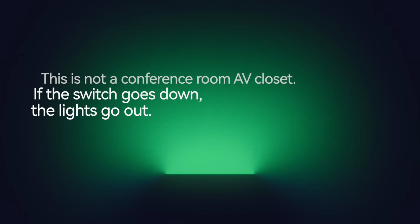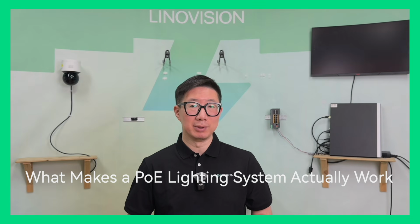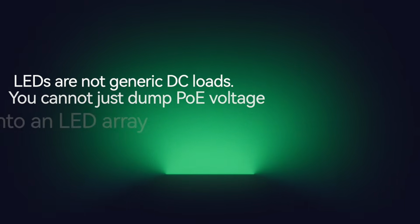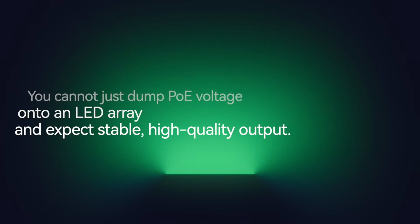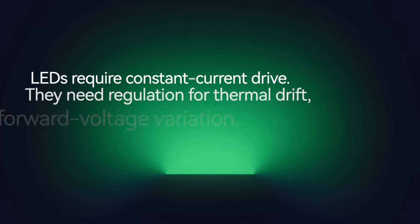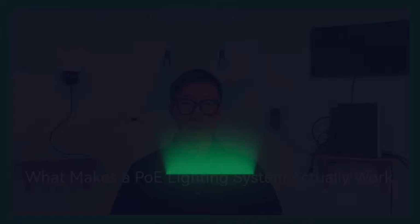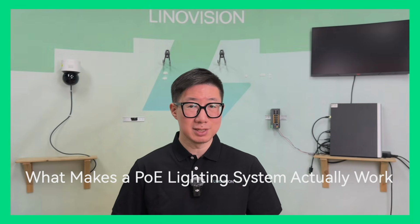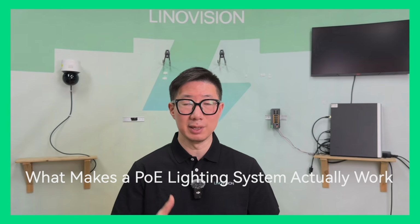Second, the fixture side. And this one matters even more than most people realize. LEDs are not generic DC loads. You can't just dump PoE voltage onto the LED arrays and expect consistent, high-quality output. LEDs require a constant current drive. They need regulation that accounts for thermal drift, forward voltage variation across the string, and precision dimming control that doesn't introduce flicker or inconsistency across the fixtures in the same zone.